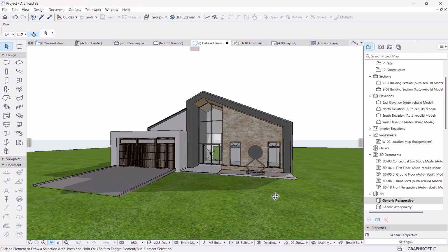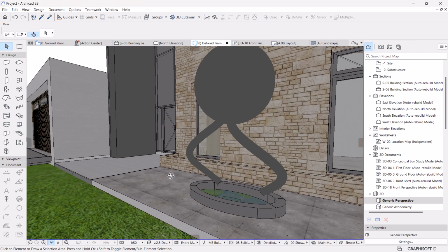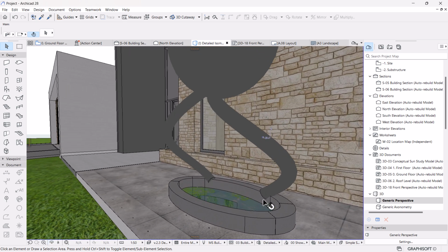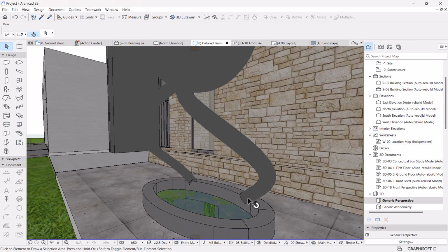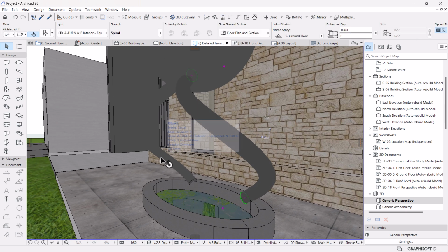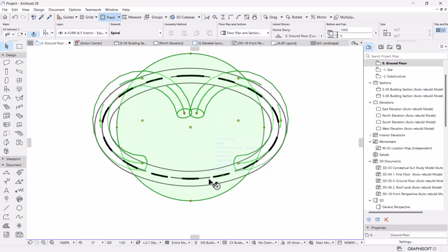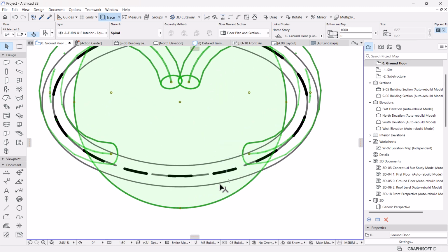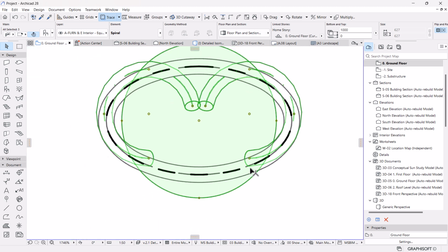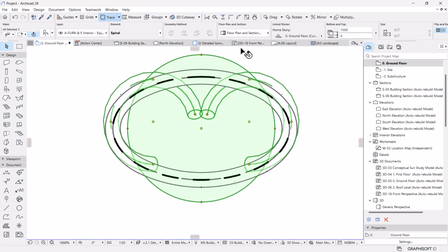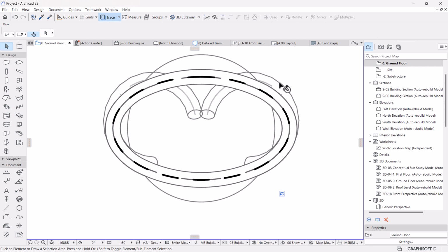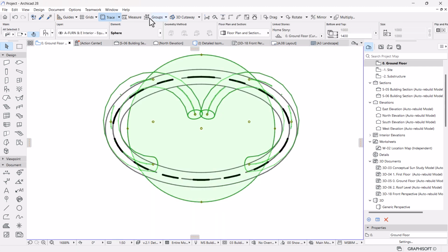artistic. Okay, so I think one last thing will be maybe detailing the base for that. So I might select the 3, then group by Control G on your keyboard, then go back to your blend view, then select ungroup.